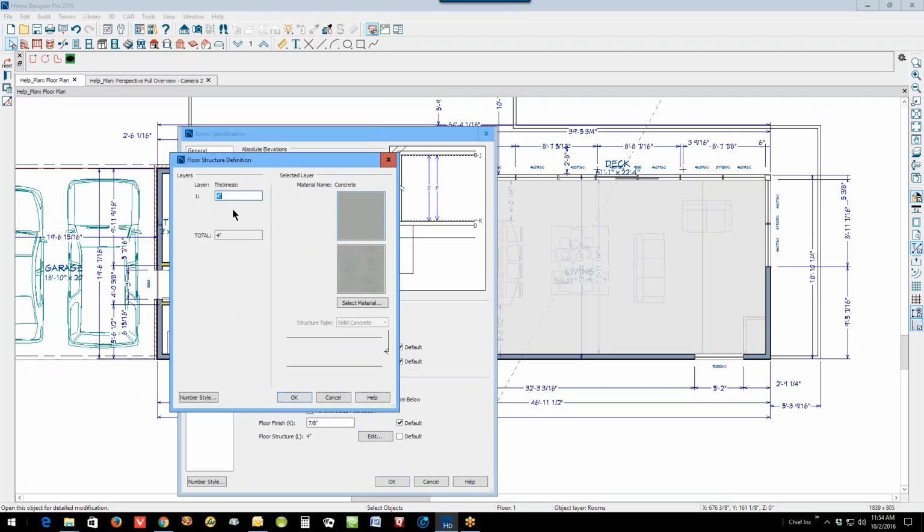And so we just put floor under this room, and then we go to floor structure, and you can see it's set to concrete, and it's 4 feet, 4 inches thick. That's not very good engineering and building technique. So this is cantilevered and transferring the load to post, so I would think it's something that's not so heavy. So I'm going to change this thickness here to 16 inches. I'm sure the engineer would probably specify something pretty thick out here, and it wouldn't be concrete.